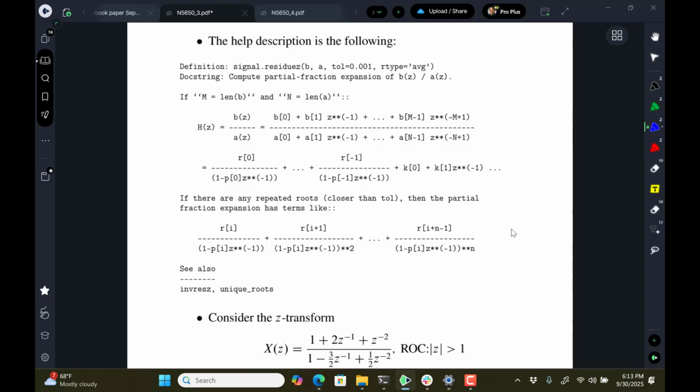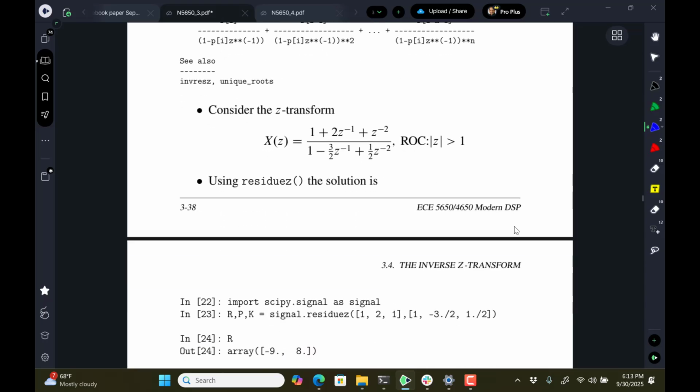So we'll go back to our first function where we had to do long division, and it uses the A and B coefficient terminology we've seen elsewhere. In lfilter, you have that B polynomial coefficient set, A coefficient set, and then the third entry is the input for lfilter. For freqz, you start off with B and A, and my function zplane works that way.